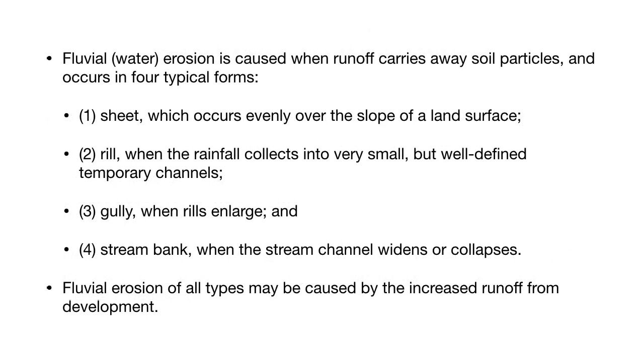Most commonly, however, we deal with water erosion or fluvial erosion, caused when runoff carries away particles, and it usually occurs in sheet erosion, rill erosion, gully erosion, or stream bank erosion and collapse. Fluvial erosion of all types is caused by increased runoff, particularly from development.